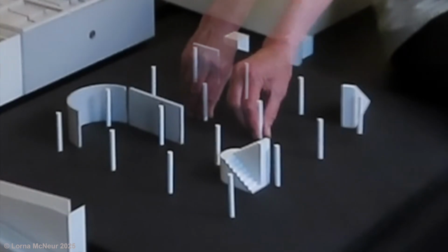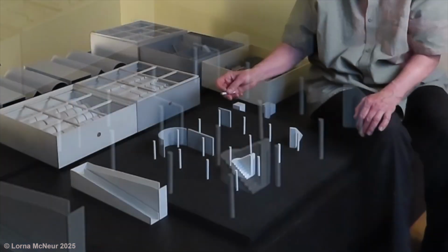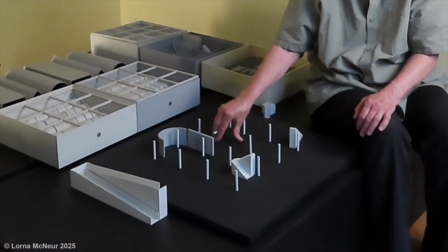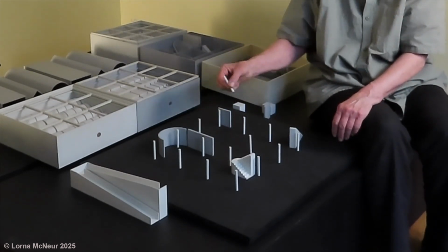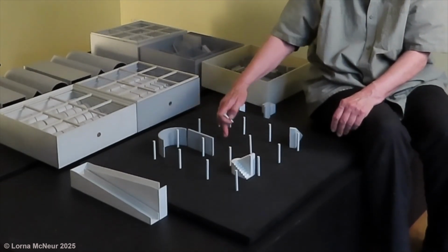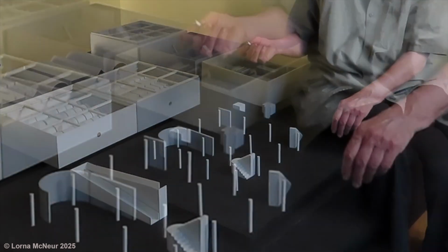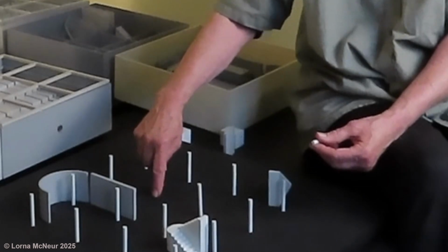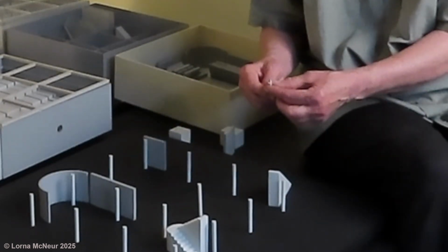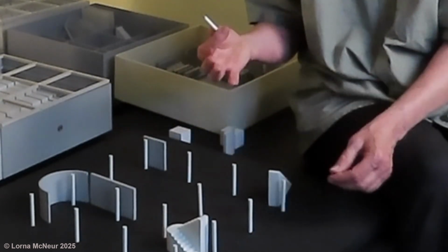Another level is the making of the model. Instead of just drilling a hole into a wooden board, having a wooden column and putting that into there, over time it will wobble. So it would wear out that hole there. So basically what I've done is to sink a copper sleeve into the base here, and also find little tubing here.